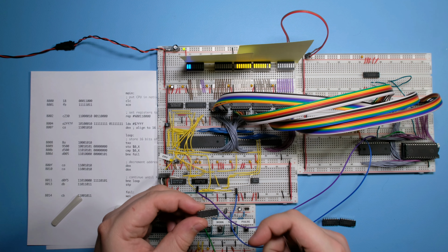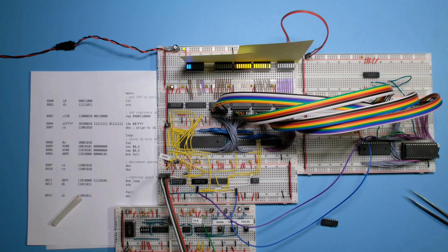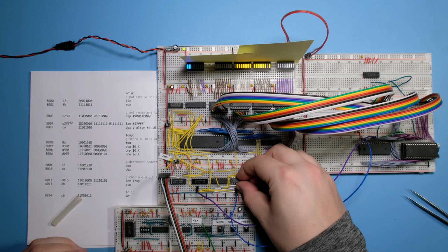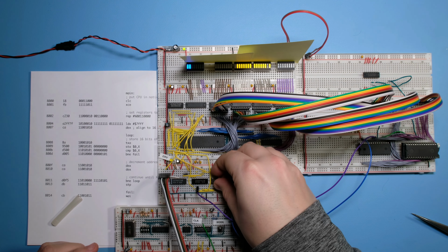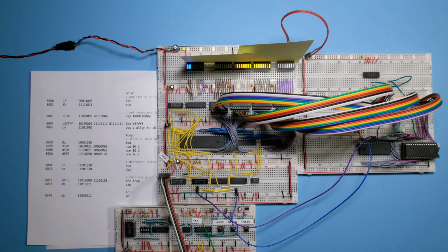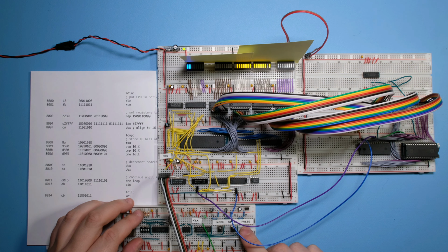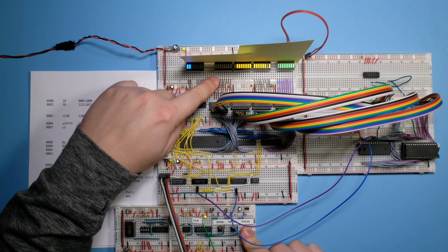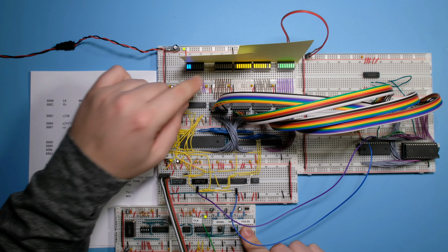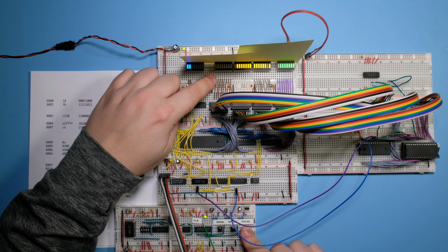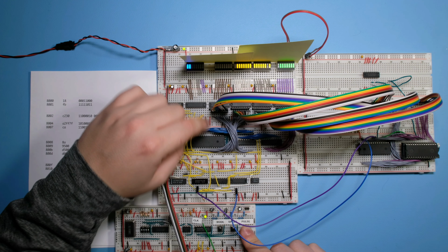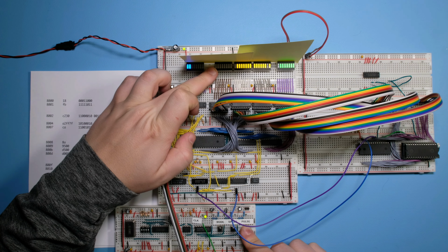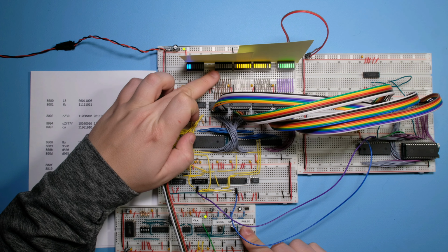So this was an HCT version, which is quite slow for what we're trying to do. And this was an HCT11, which is also quite slow. There we go. Let's try this again now. So let me do the write. And as you can see, we are not latching the bank address anymore. So this was a correct fix. Now the glue logic here is much faster, and so we're able to latch the correct bank address, which is 0, at the right moment here.